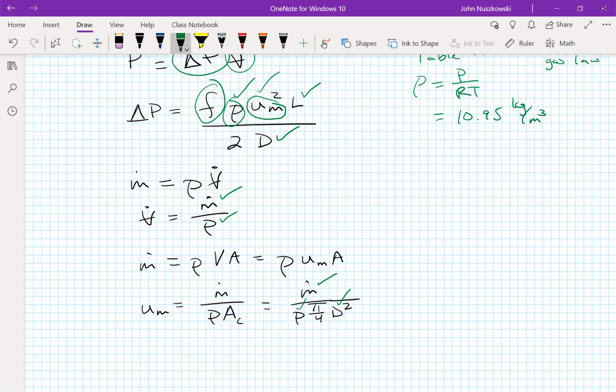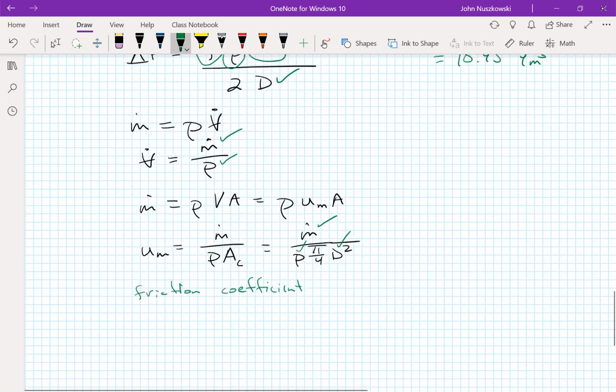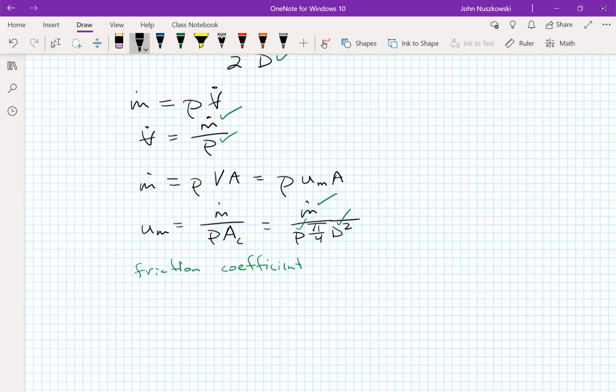So that's where we get to make the easier case here. Otherwise, yes, we got to go to that Moody diagram and figure out what our friction factor is from it. Or if we had a smooth pipe and turbulent flow, there is an equation for the friction factor. But if not, we have to go to those surface roughness and those equations you dealt with in fluids, right?